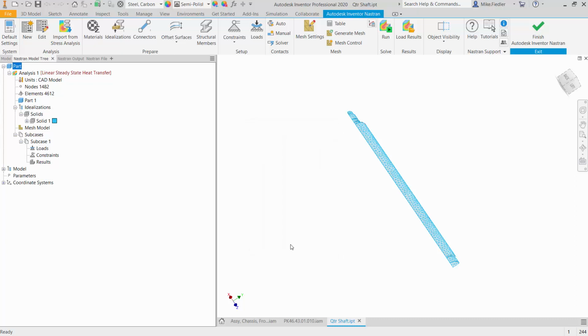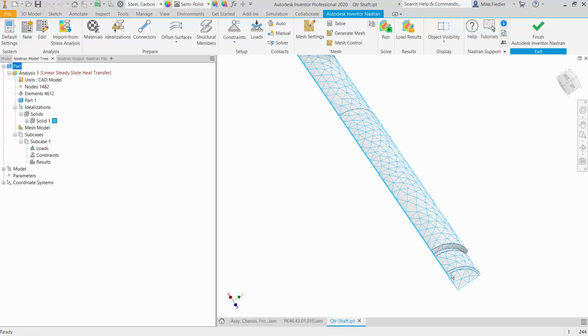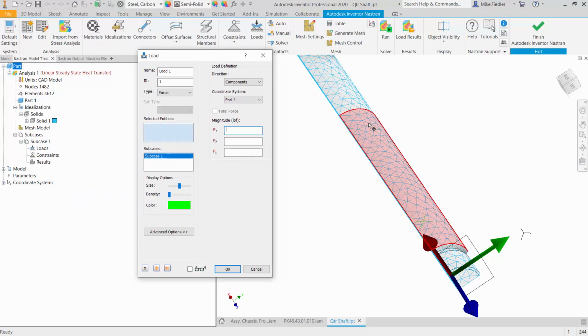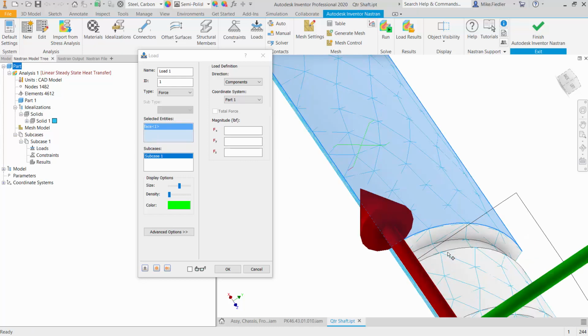Okay, so now our material has been defined, our mesh has been defined, our analysis type has been defined. What we're left with here are defining our loads. And if you remember, we are in a thermal analysis, and this region where I created that split line on down, these are the surfaces that I said somehow we're able to cool these to 0 degrees Fahrenheit. All right, so we can do that in a couple different ways, but for this one, what I'm going to